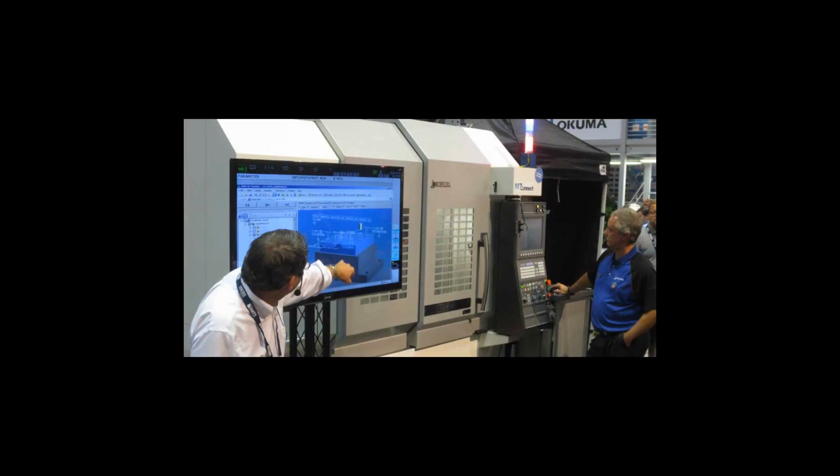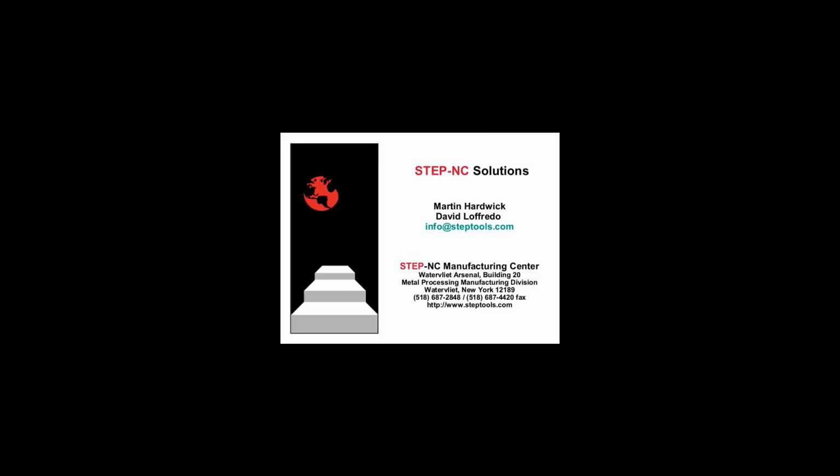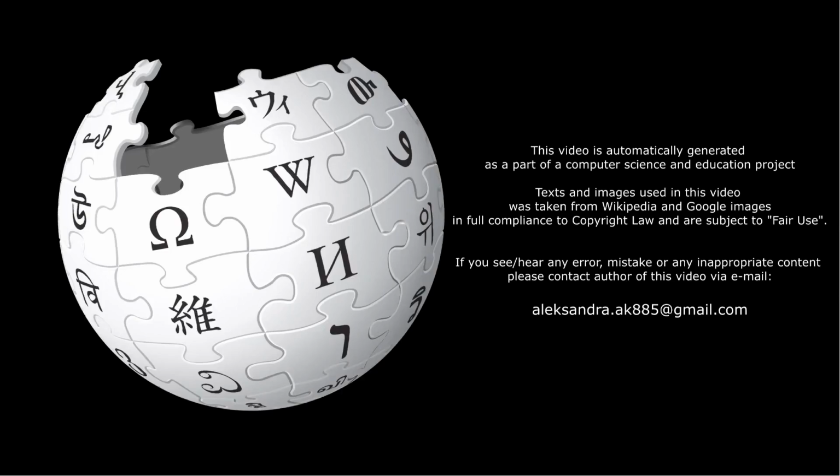Motivation. Input to a CNC in the ISO 6983 RS274D G-code control language is often machine-specific and limited to axis motion commands. The machine tool is given little or no information about the desired result of the machining. STEP NC allows more information about the machining process to be sent to the machine control and adds new information about the product being machined.